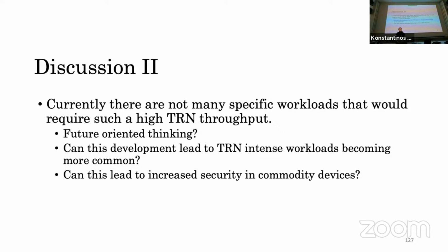If nobody has anything else, I just wanted to add something that just came up, in terms of compromising, thinking about attacks such as RowHammer and so on. Wouldn't this expose the random number generator to a potential attacker, especially if we're talking about a system where, as you mentioned, the paper hasn't really talked about running this concurrently with other tasks, but say you are running it on a system which is also running other processes? I see this as a big vulnerability where you could potentially read out some of the random states from the RAM and thus compromise your random number generator. This isn't, for example, the case with really dedicated on-chip hardware, which is isolated.